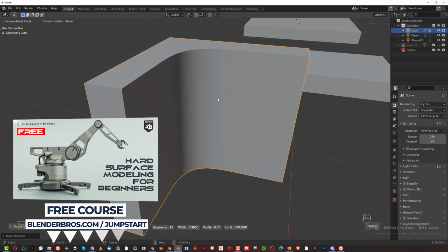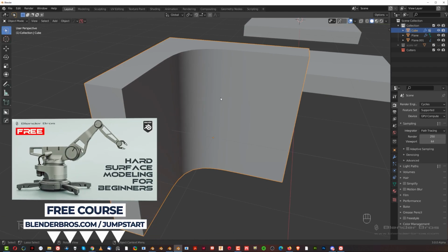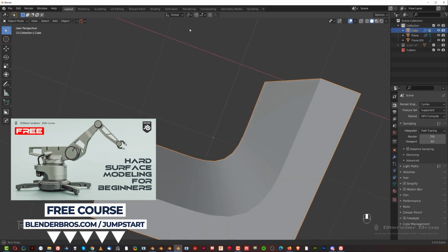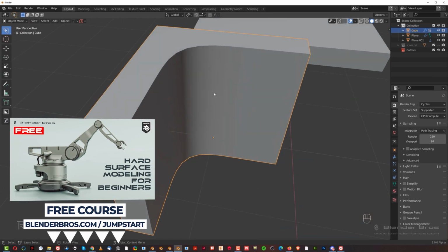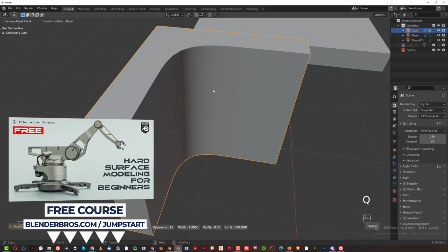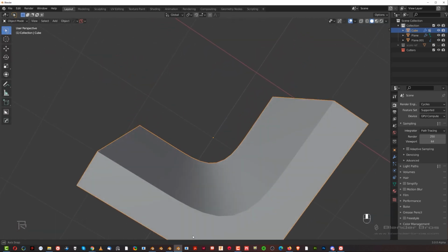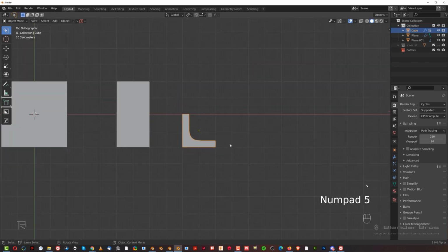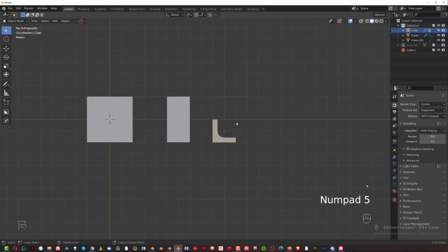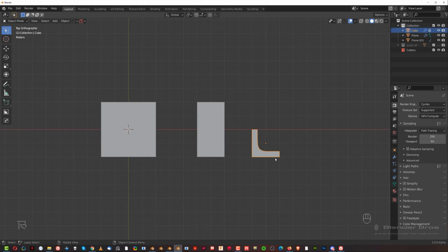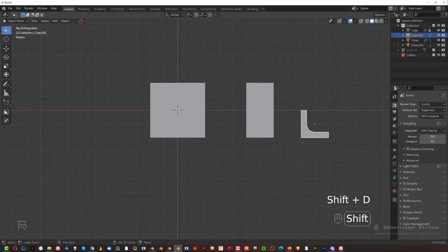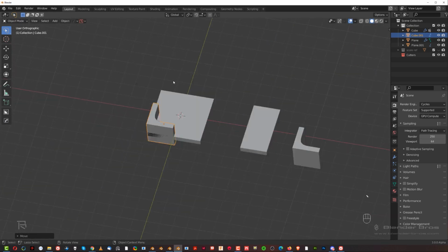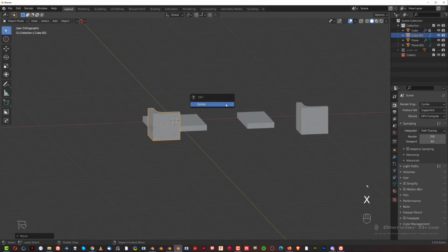Okay, now you can check if a lower bevel is going to be okay. So let's go to bevel again and lower it to 10, and I think 10 is going to be completely fine, although 12 is probably a little bit smoother, so I'm going to keep it at 12. Okay, all right, 12 is good. Yeah, I kind of like that. Cool. So we got the first corner piece, okay? And these corner pieces are going to fit perfectly on top of this floor. So Shift D, and you can snap it with Control perfectly to your floor. And of course it needs to be a bit higher, so we need to fix it.